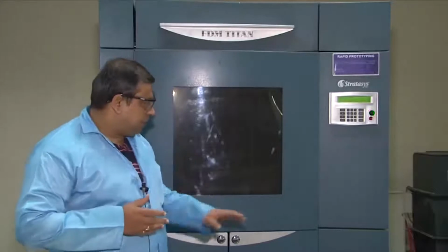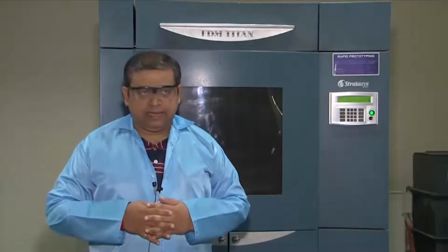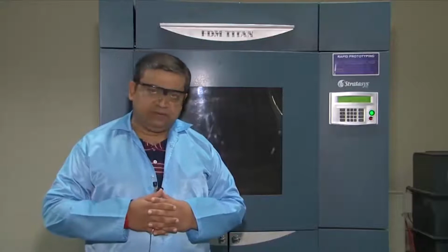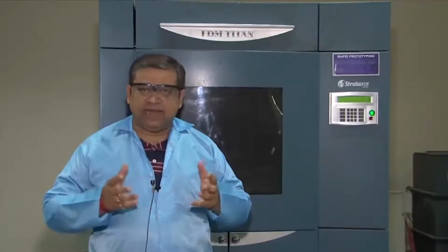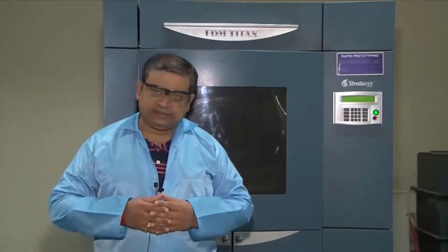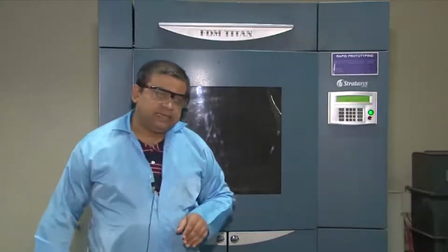Okay. So rapid prototyping is about sectional printing of material. It is also known as three-dimensional printing. The whole idea is that if there is any complex feature or shape as a CAD file which is available, the system tries to section that particular CAD file into small elements, okay? And each element is being deposited by means of plastics, which are typically two in kind. One is either polycarbonate or ABS plastic, and this particular machine has the capability of handling only plastics.